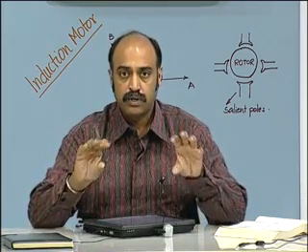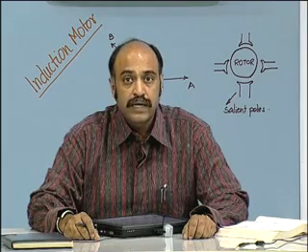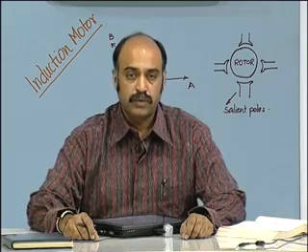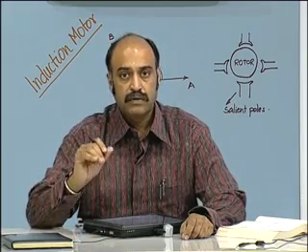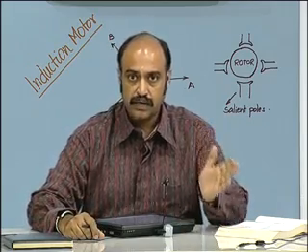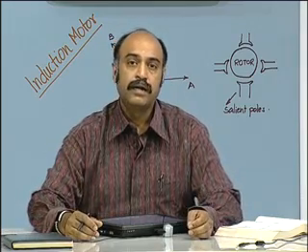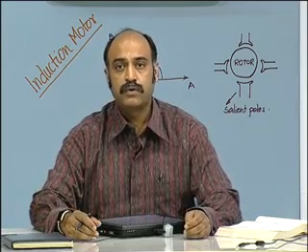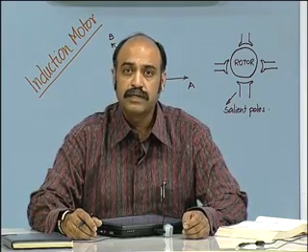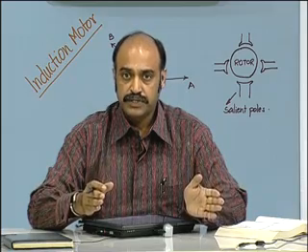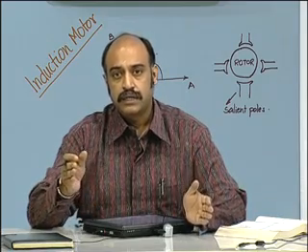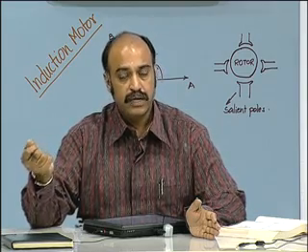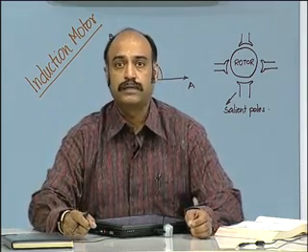So you have the energy which is moving from the electrical domain into the magnetic domain, and you can tap the energy in the electrical domain or in the mechanical domain or both, depending upon the type of the motor. So in the induction motor you have two main categories. The squirrel cage induction motor, where the rotor is shorted, you cannot take any electrical energy from the rotor. So all the energy can be taken only from the mechanical domain. So you have the electrical, magnetic, mechanical domain as the path for the energy. And in the case of the other category, the wound rotor induction motor or the slip ring induction motor, the electrical domain energy enters the machine, goes into the mechanical domain, and the energy can be tapped out either in the electrical domain of the rotor or the mechanical domain of the rotor.